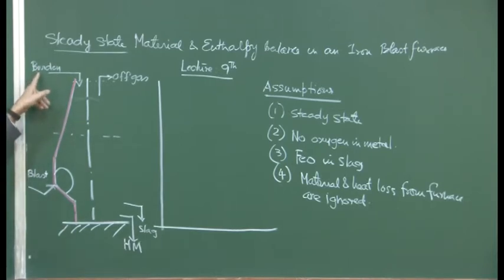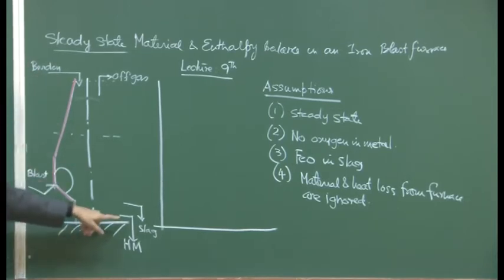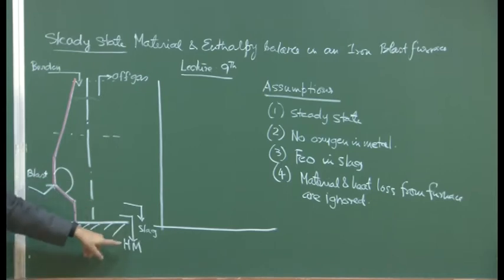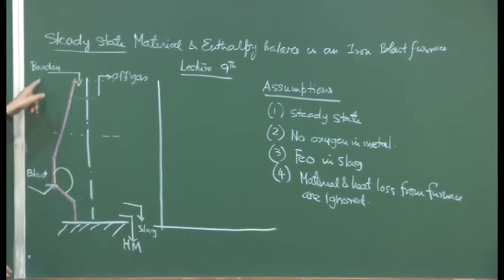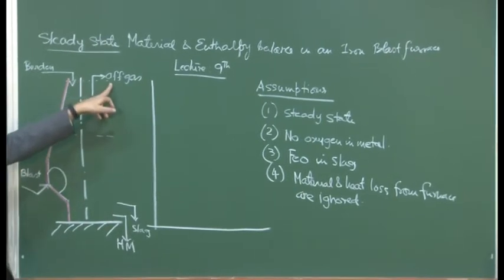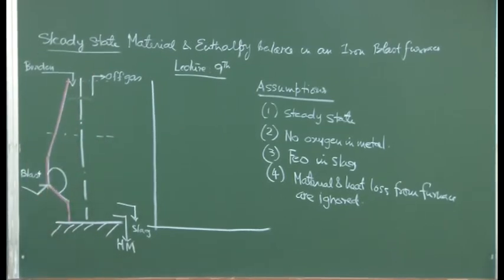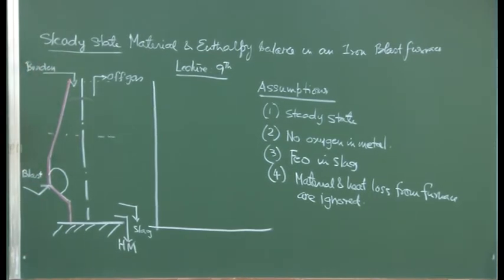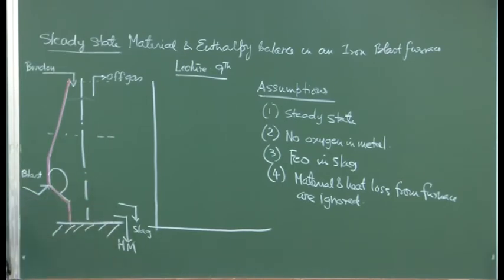Every iron ore is going to be reduced, iron is going to be manifested in the hot metal, and whatever oxygen is there will manifest as carbon monoxide or carbon dioxide. There is no necessity of any slag. So, an ideal blast furnace operation with pure coke as well as pure iron ore means that the slag phase is typically absent.